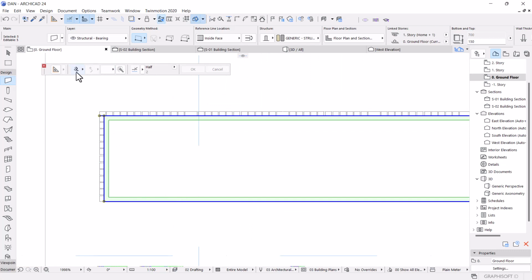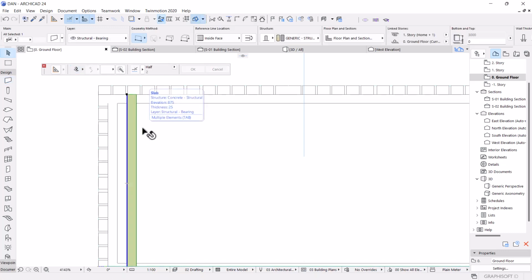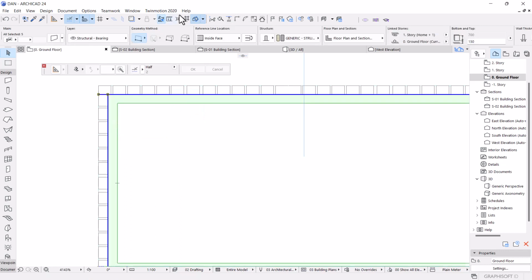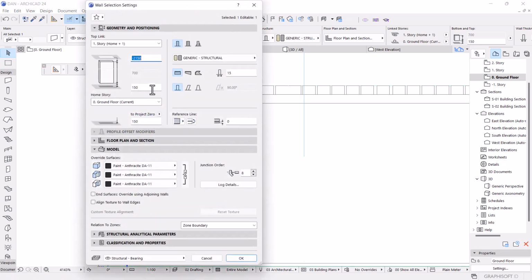So let's offset this side to 15. It's offset by 30. Let me just drag, suspend groups, Ctrl Shift plus D, drag it by 30, and Ctrl T. We want it to be 75.